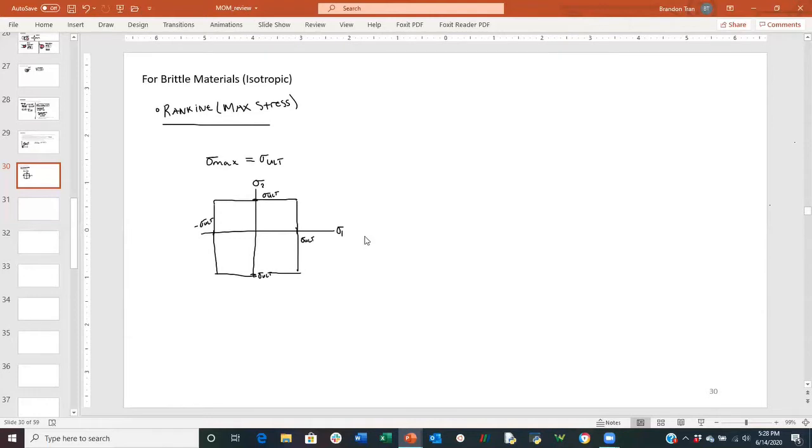Okay, so essentially what that means is that in a 2D case, if your principal stresses lie outside of this failure envelope, your part's going to fail. So that's how to look at it graphically. Now, how to look at it using analytical methods, the first thing we do is we establish failure criteria for ranking. So I'm going to say if the ultimate compressive strength here, so they'll give it to you, they'll document it, ultimate compression strength without the negative. We just put the negative here for completeness of relating literature to documentary.